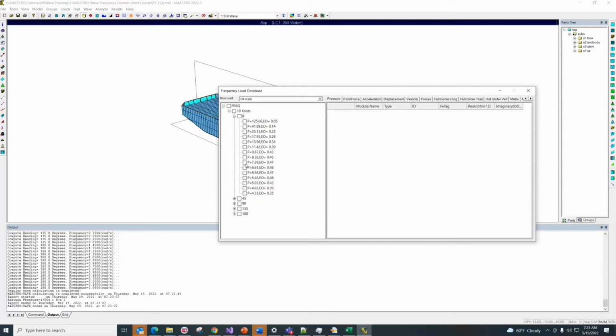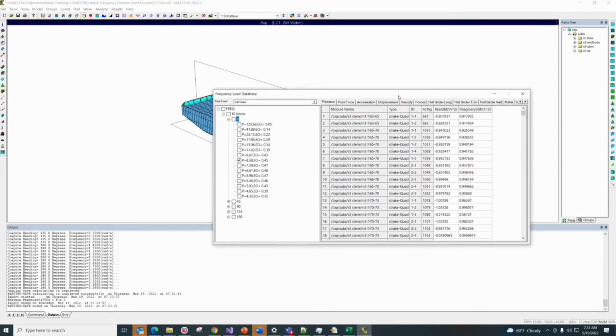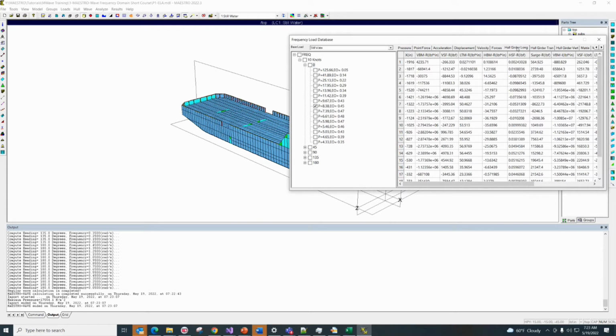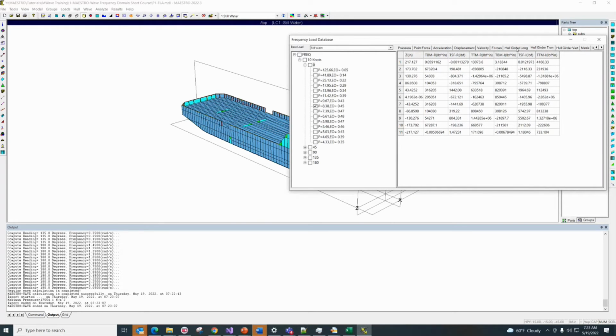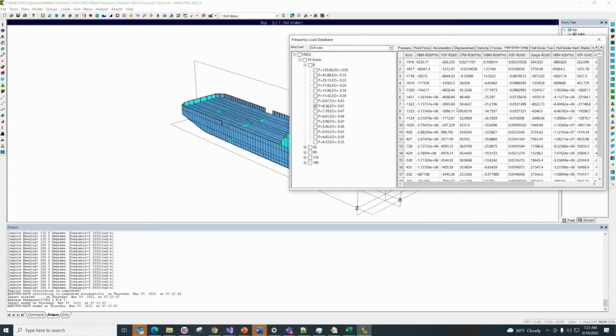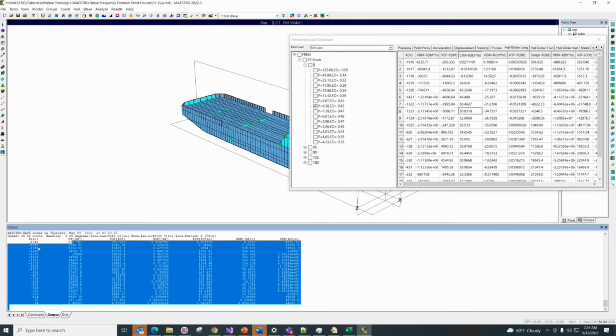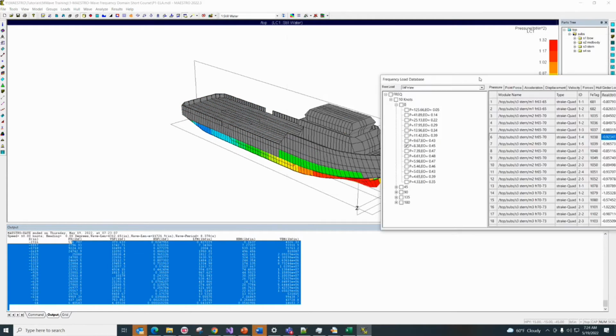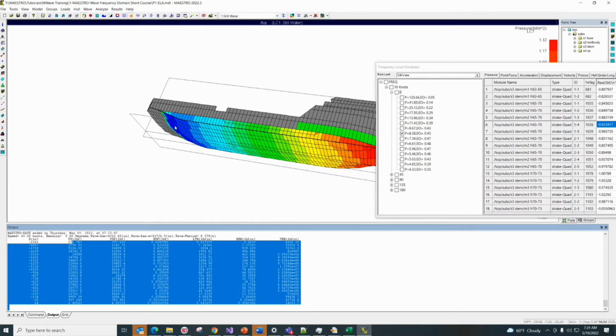Let's say 8 seconds. So this shows you the dynamic pressure of 0 speed. All the panels is the pressure as a point force, longitudinal bending moment, transverse bending moment. So if you have a catamaran, that becomes important. So all this data is for the unit wave loads. If you right mouse click, it's going to give you some information. You want to list the bending moment for each section, the IO gives you that. At the pressure level, if you right mouse click, it asks do you want to see the pressure? So you can see the pressure of this run. So you can see it's negative.